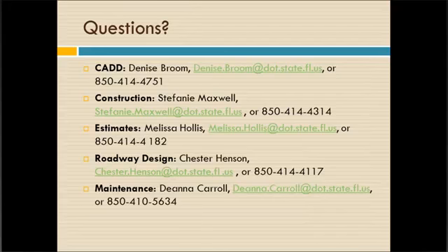We used to cover it by MSP, and what we're trying to do is get rid of that, where it's in the specs and specs clarify exactly how it would be used. So 710-90, you do have it itemized in your summary quantities. You do not have quantities for it because it is lump sum, but you do have the different markings that are included under 710-90, which are basically your final markings.